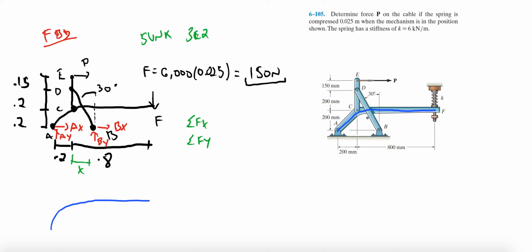The way you recognize it, you just look at the assembly and you see that it's not split. The drawing itself doesn't show any superposition of lines. For instance, this line is a superposition, so it means that it's a different link. And this line is also a superposition, so that's another link. So really this is a link on its own. From A to F, that's a link on its own. So link AF,